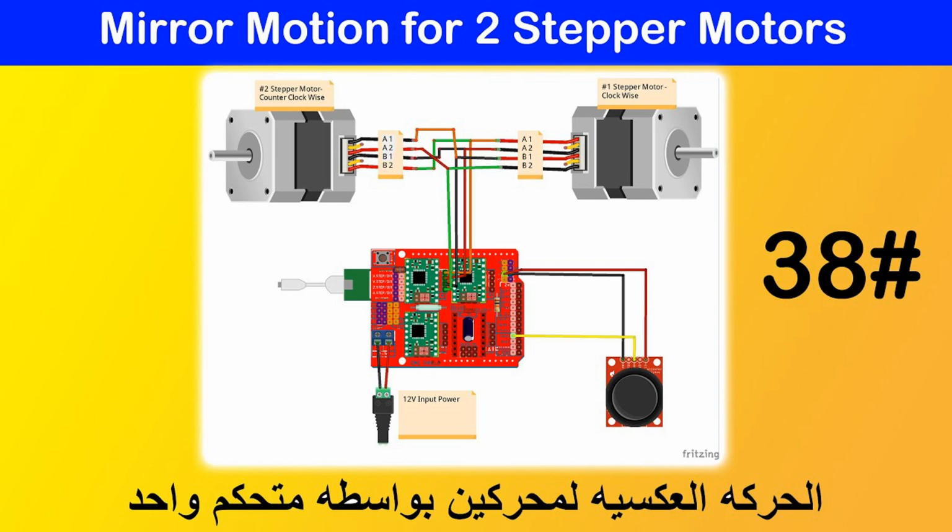4. Full step and half-step stepper motor drivers. Full step drivers. These drivers energize the windings fully in a stepwise fashion. In full step mode, the motor moves in large increments, one full step per pulse. Half-step drivers. These drivers alternate between energizing one winding or both windings, effectively doubling the resolution compared to full-step drivers.